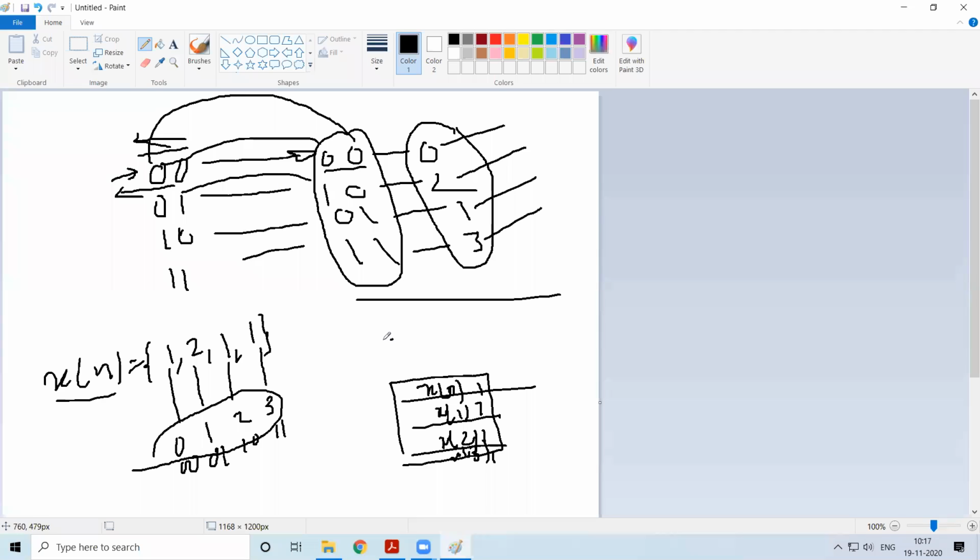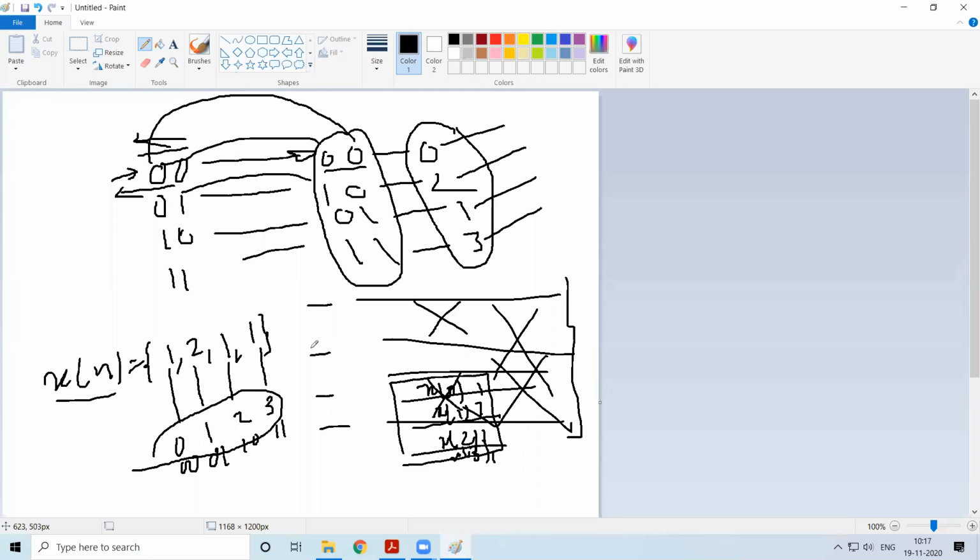So if you remember, you write the butterfly diagram, remember all these things. So you draw the butterfly diagram and then you try to give the inputs, and here you'll be getting the outputs. So if they are given in proper form here, that is without bit reversed, here they'll be in bit reversed form. So we should take down the samples in proper order. So this is one special case with respect to your DSP.